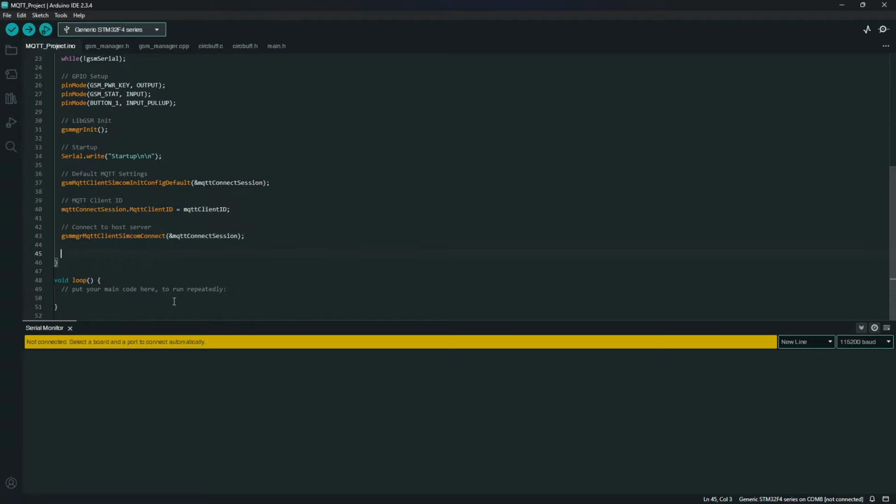The next thing that we want to do then in our case is immediately once we've connected, I want to send out a subscribe message. So I'm going to make a temp character array here. Sorry, that shouldn't be commented out. Of length 64, for example. You can make this length whatever you'd like depending on what you're going to output. And I'm going to say sprintf. I'm going to write that to my temp. And then I'm just going to say subscribing to a string value.